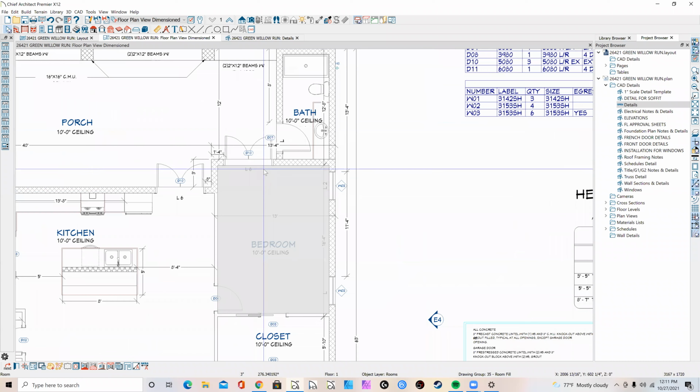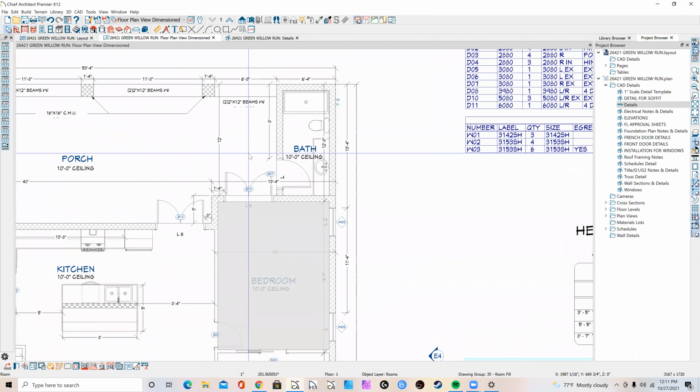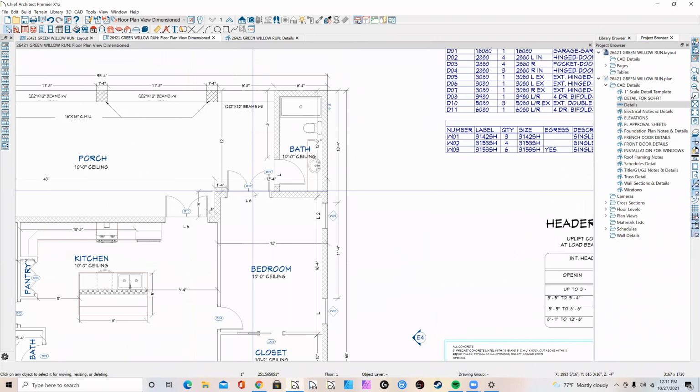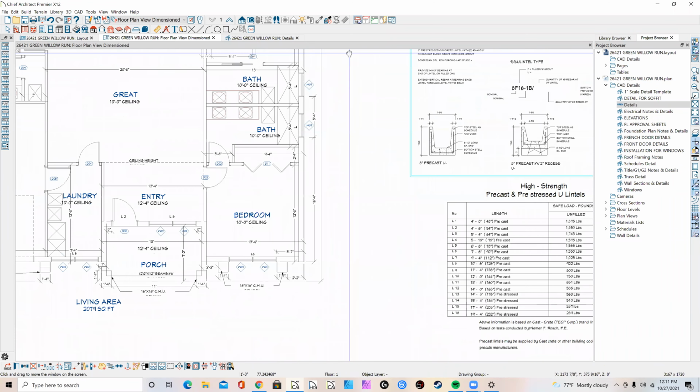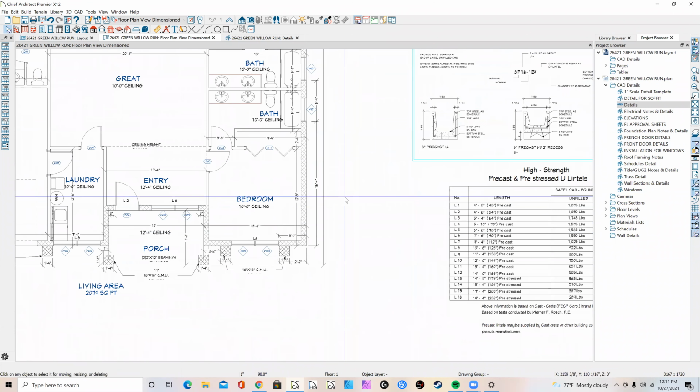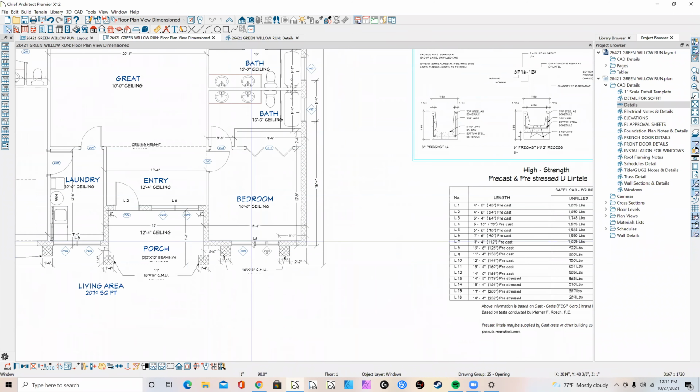This bedroom has a door. This door goes to the back porch. Therefore, this is your fire exit. Don't need to use the window to get out. This bedroom does not have access to the outside of the house. Therefore, these two windows are fire exits.